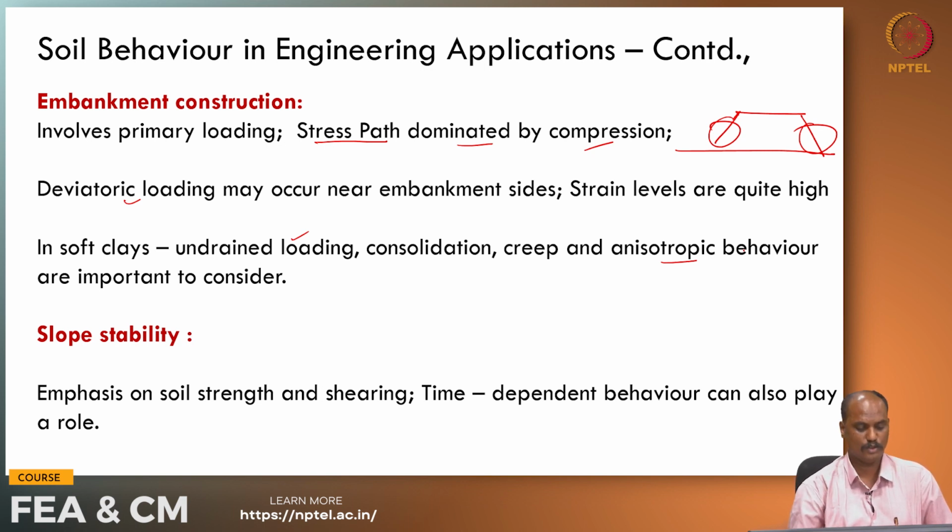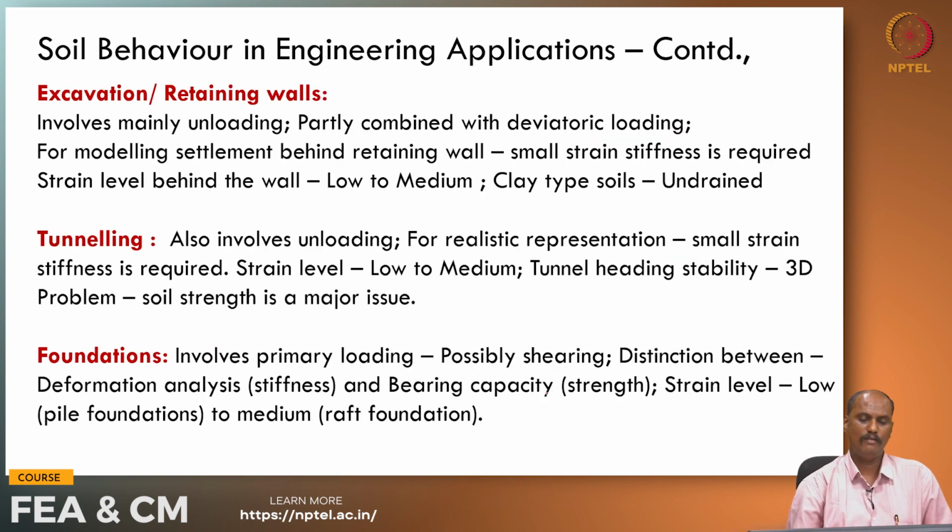The next aspect is slope stability. The emphasis on soil strength and shearing is very important, and time dependent behavior also plays a vital role. Continuing soil behavior and engineering applications with excavations as well as retaining walls, these problems are a bit unique. In the sense that they mainly involve unloading, whereas in the previous cases the main point was loading problems. Here we have unloading problems, partly combined with deviatoric loading.